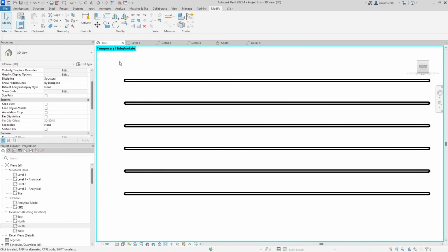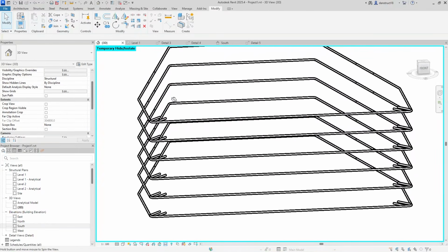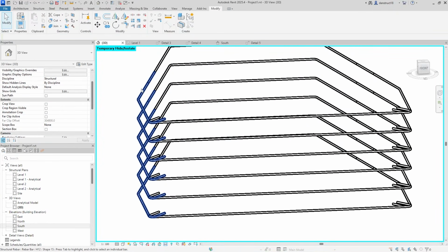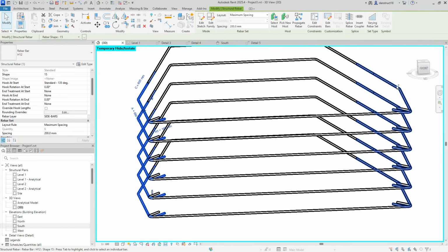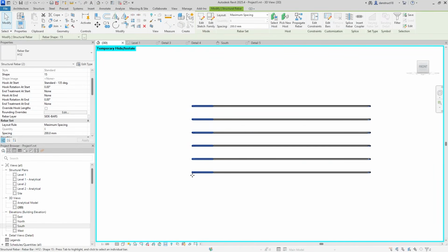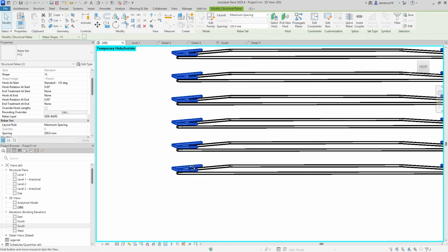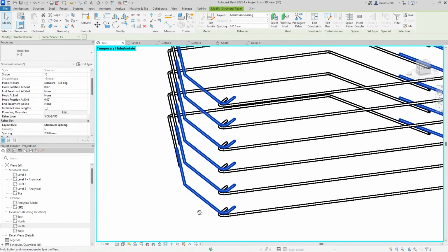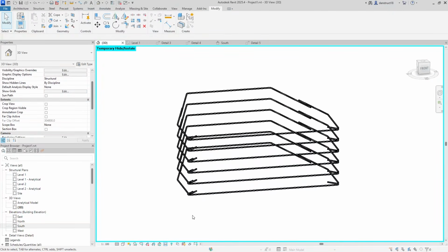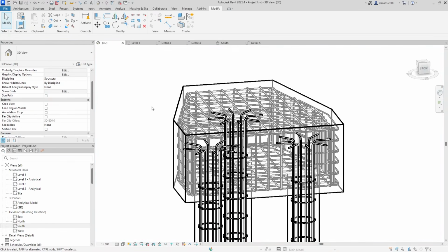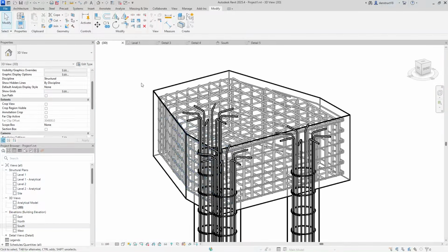Now I'll come back into the 3D view, and I'm just going to orbit around, and we don't want the bars to clash like this. So I'll select this bar here, hold down the control key, select this one as well, and click on the front view. I'm going to use my arrow keys to nudge it up, so just to show, that they lap. All right, good. So once you've done that, you can just click this button and reset. So we have a very nice detail here.